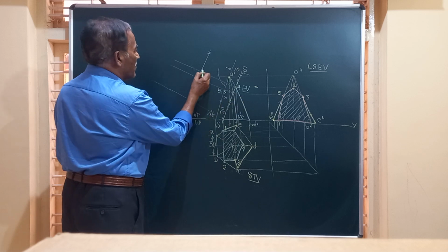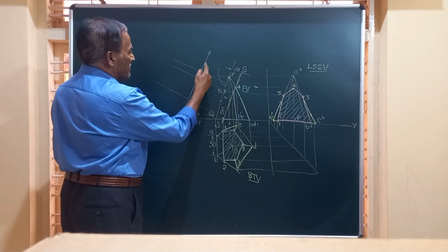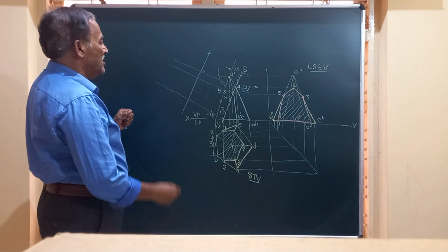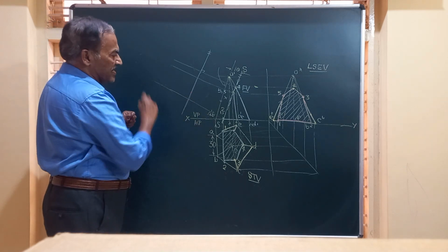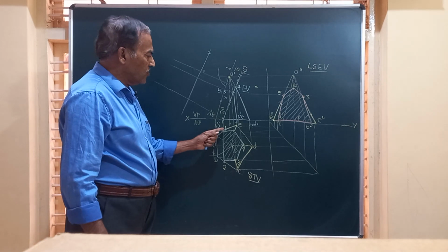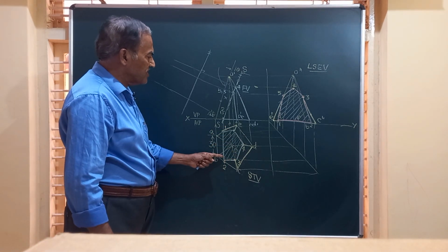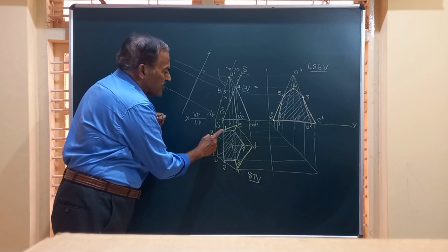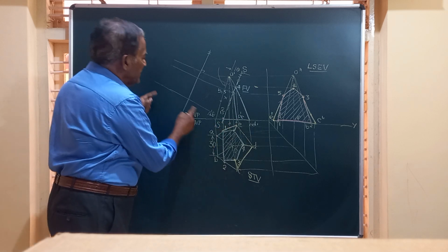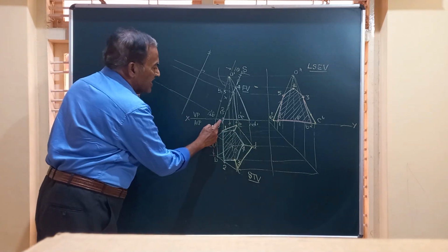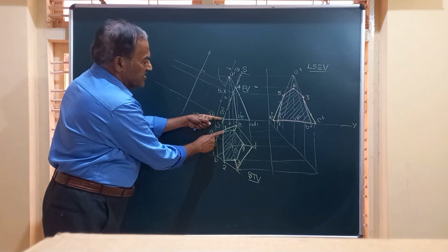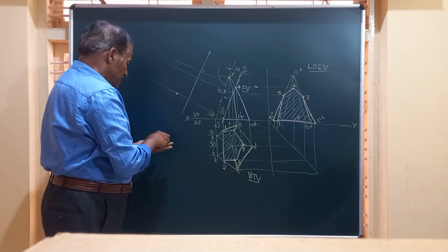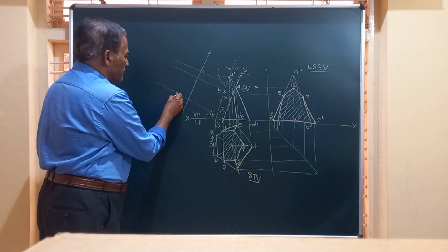So we have drawn all these lines perpendicular to this line drawn parallel to SS. Friends, on these lines, we have to obtain 1, 2, 3, 4, 5, the distance of them, measured from XY. Suppose if I want to mark 1, 1 has to be marked on this line at a distance of this much, taken from XY. Say, I am going to have this point 1 marked here.